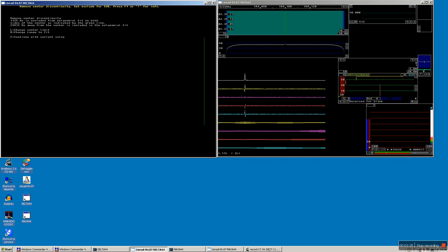And the range to fit, I make it bigger, 35 kilohertz, because the audio filters in the IQ Plus do not affect the phase below 35 kilohertz.